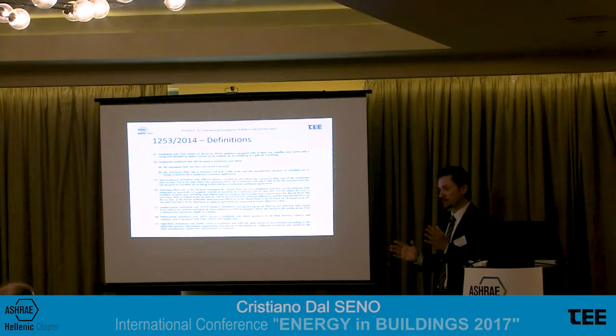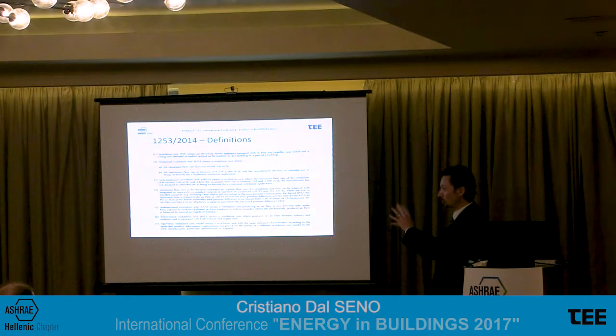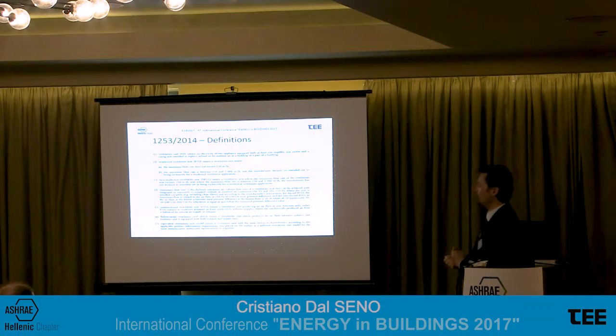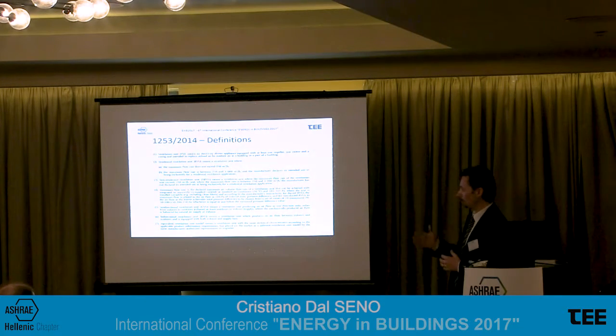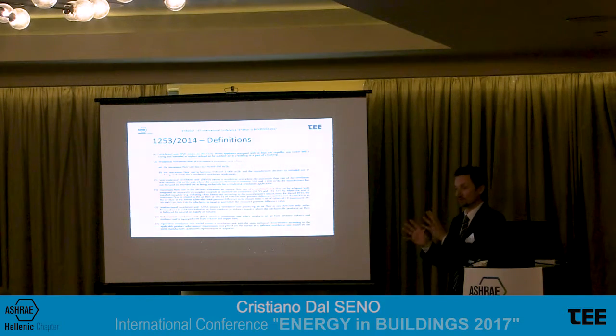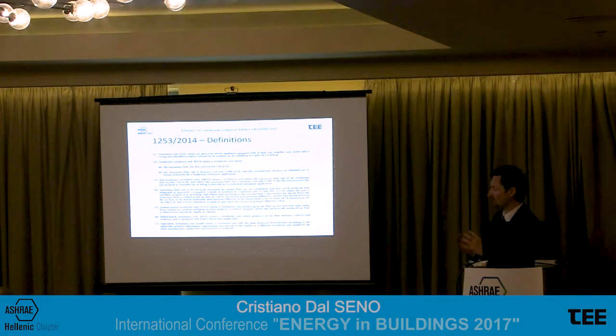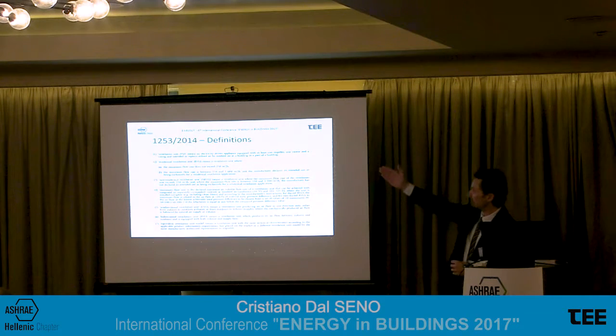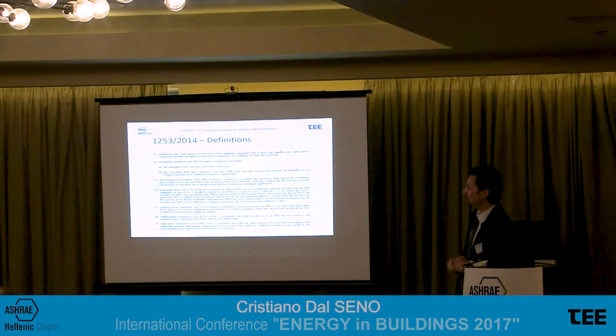All the other air handling units should be considered in the framework of this technical regulation given by the European Community. Then there are some exceptions. We will discuss these exceptions looking at the different definitions given by the regulation, but more or less we can say lower than 1,000 cubic meters is residential application, higher than 1,000 cubic meters is non-residential, generally talking, commercial application. The commercial or non-residential application we are discussing is to be included in the framework of the regulation 1253.